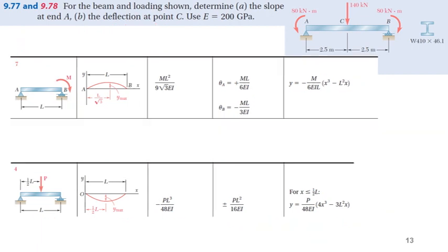Okay. Now let's see this one. Now we're talking about theta A, sorry, due to moment about B. No, sorry, moment about A. Now if you look at this equation, for this it will become theta A, and ML divided by 3EI, not 6EI, because that one is giving theta B. But in the current situation, we are considering MA over here, in the same direction, so this slope will be this value, but in the opposite direction, so the sign will be positive.